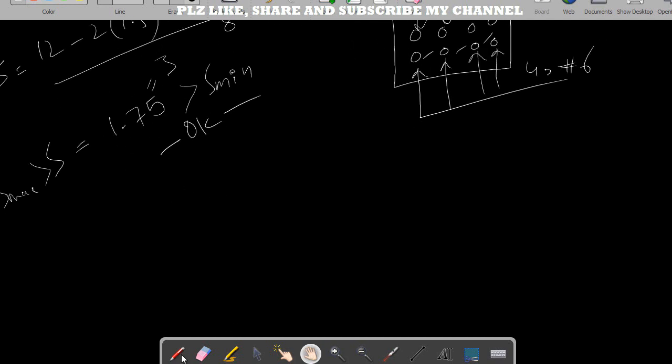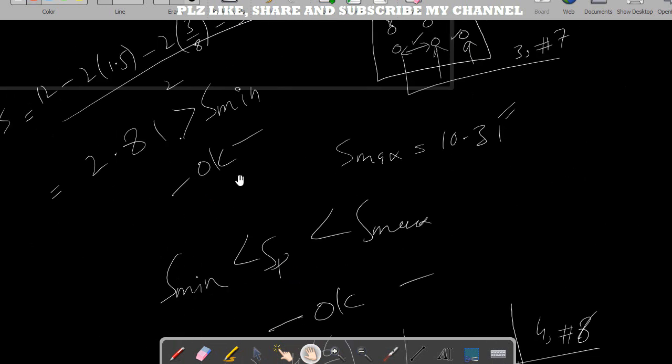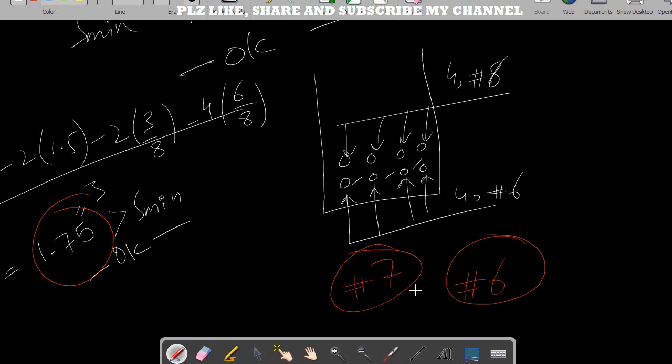But here, if you can see, the clear spacing is 1.75, while here the clear spacing is 2.81. So this one will be more preferable as compared to the lower one, but make sure that number 7 bar is really available in the market, right? Because sometimes it is not available, so in that case we prefer number 6 bar, right?